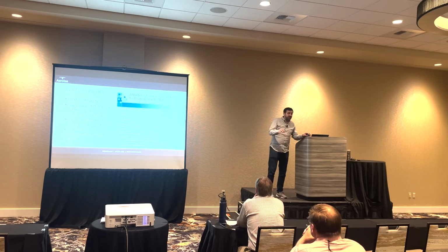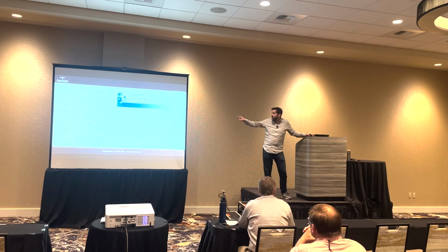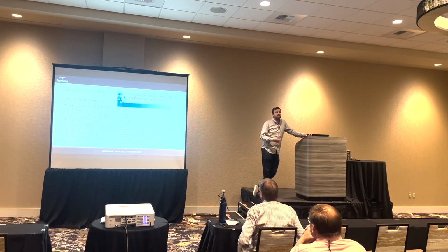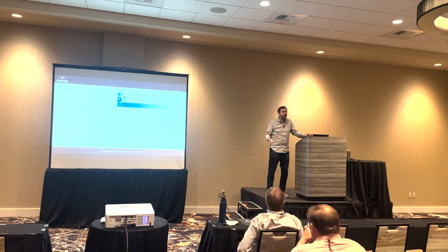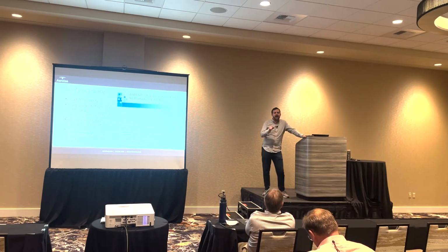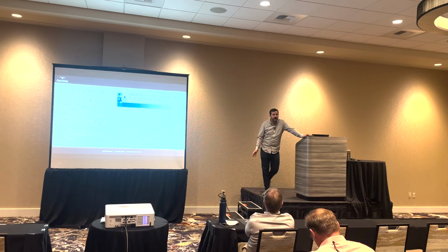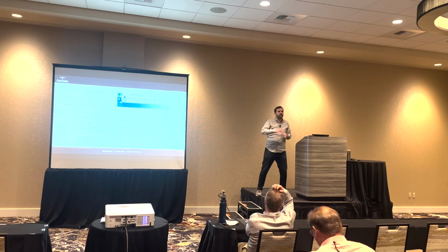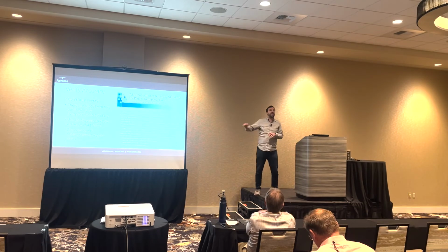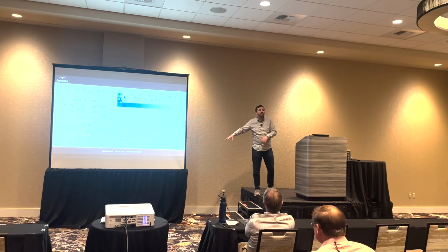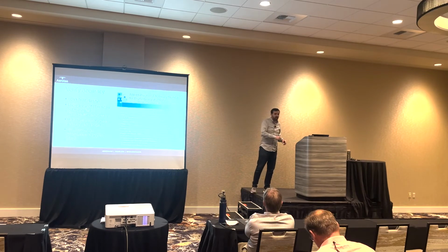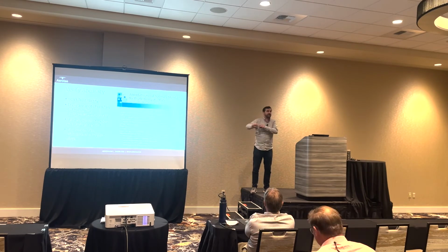I'll give you a little bit, and if this isn't enough, I recommend actually looking through this, because when I say a tenth, what I typically mean is a root mean squared error. Your RMSE is going to be your gold standard. It has replaced all of the national map accuracy standards of the past. An RMSE is very close to a standard deviation, right? It's the average of error across all of your points, but it gives a much heavier weighting to anything that's far off. So if you have 9 checkpoints that are all perfect and 1 checkpoint that's a foot off, that's really bad.